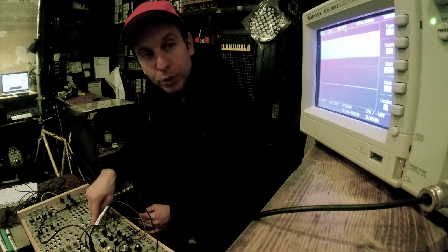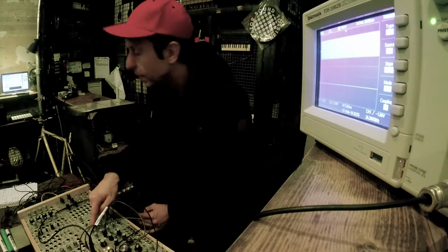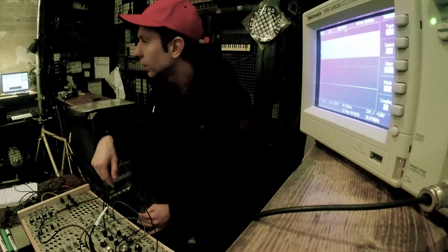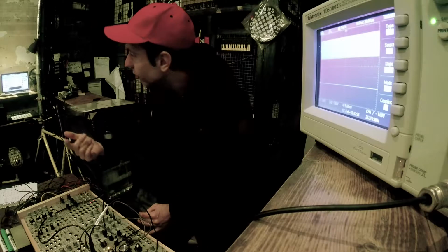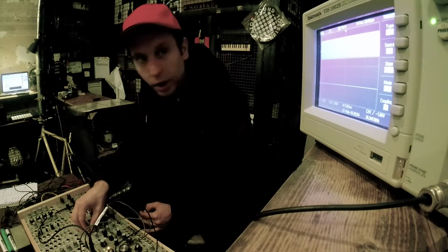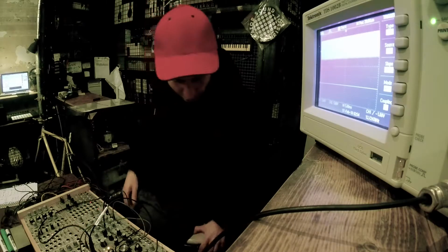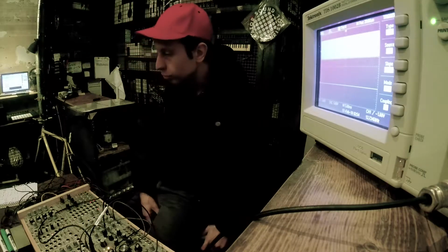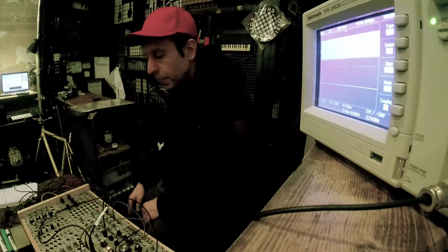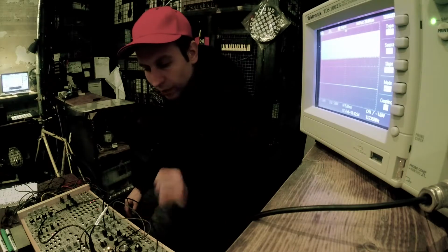And now I'm only putting in plus 5 volts. This is my max plus 5. If you remember from the first class, my hack to make plus 12, probably go up to 30K, 50K, whatever. You remember my filter went up to 60K like this? So that's really useful to know, that you can burn your modules way out of their range if you have these DC signals in the CV input.